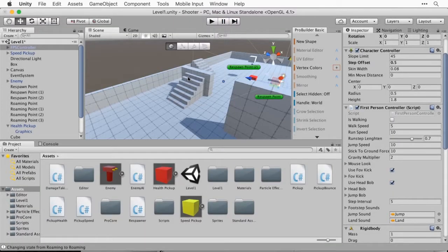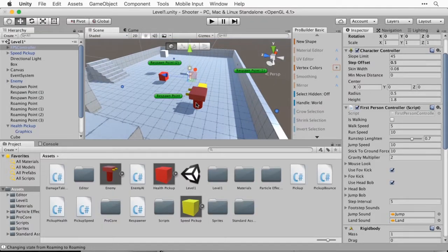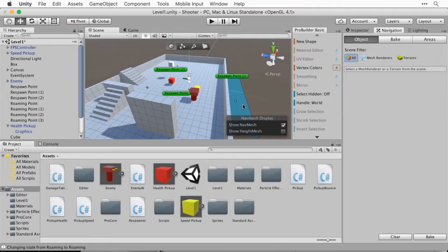One last thing that we'll do is it's important to make sure that our character does not walk through walls. Our enemy does not care about the position of these walls. Additionally, we haven't yet told Unity about the new configuration of the world. Let's go back into the navigation pane and click on the Bake button. You'll notice that with the navigation pane turned on, the navigation mesh is shown as it was before, that is, before we deleted the floor. So this is now incorrect. We'll click the Bake button again, and Unity will calculate a new walk mesh. You'll notice this includes things like the stairs, because stairs can be climbed.